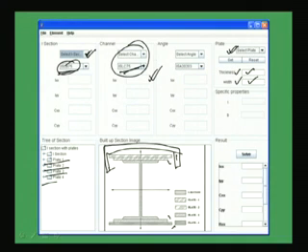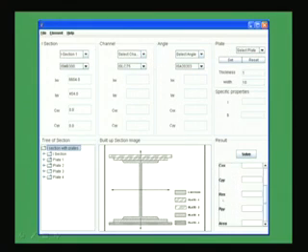Then when you put solve, you will get the results: IXX, IYY, CXX, CYY, RXX, all the properties of the built up sections. After that you will get RXX, RYY, and area. Here the scroll button is there, from which you will get all the required properties, right?